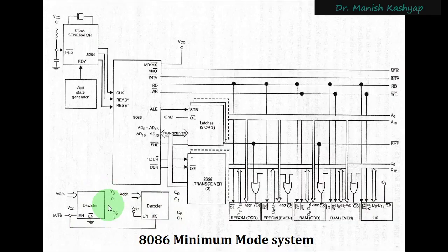Once you have decided that you are using the memory chip, then in conjunction with one of the signals that you will get as an output from this particular set of chips, which is BHE bar, and this A naught of this address bus completely, you will be selecting even and odd banks, right? So that you can write a particular word inside the memory, or you can write even or odd byte of the memory in the appropriate cycles, right? In that way, these things have been connected here.